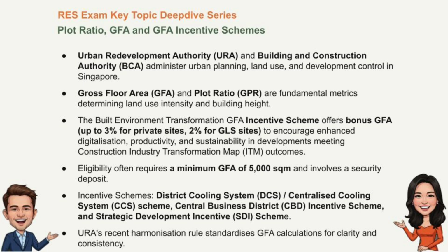Exactly. And if their old IBCP space was already GFA exempt, they might be allowed bonus GFA equivalent to the size of the space they decommissioned. Again, any proposed new uses for this freed up or bonus GFA could be subject to LBC. Plus, any small M&E spaces they need just for the connection itself, like a heat exchanger room, can often be counted as bonus utility GFA too. So incentives all around to join the Cool Kids network. But surely there are rules. Can any building just claim this?